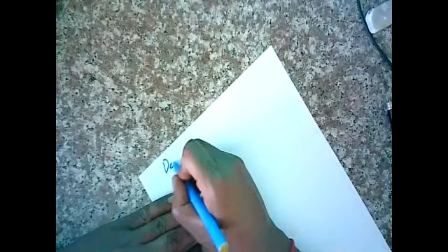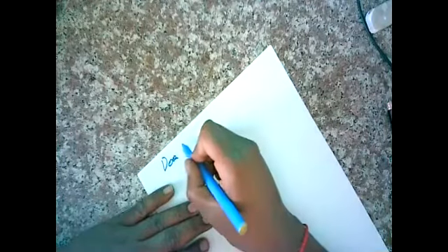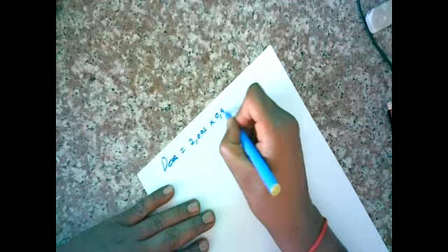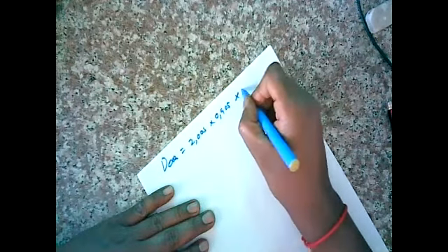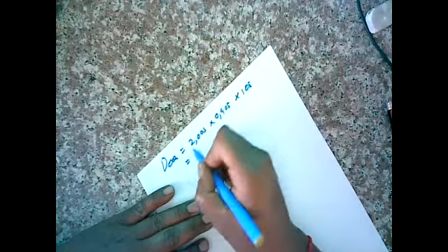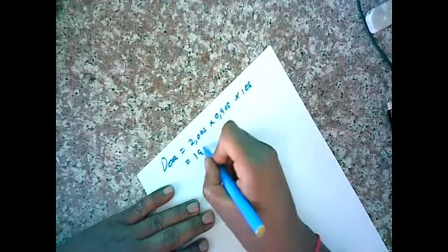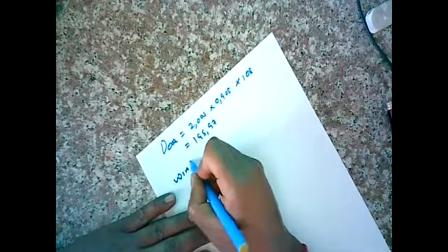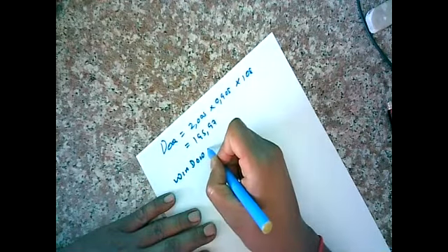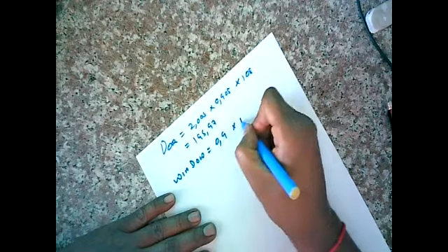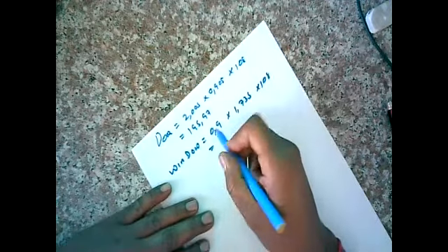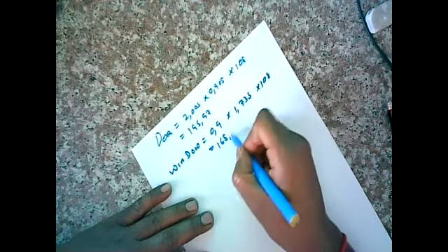And here, let's say door. Our door is now 2.005 times 0.905 times 108 because it's a single brick wall, and we're looking at 195.97. And our window, we know the dimensions because that's given to us, is equal to 0.9 times 1.735 times 108, and we get 168.64.